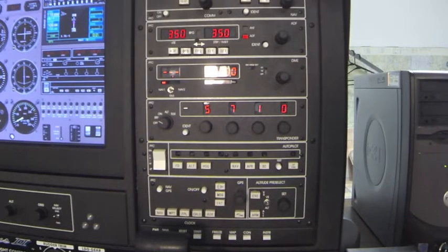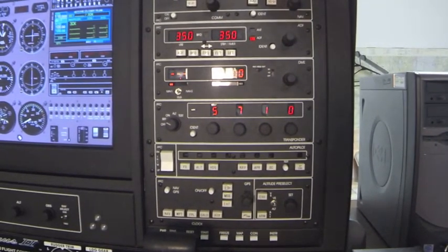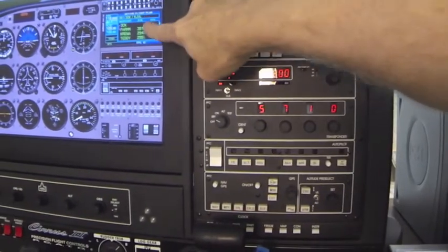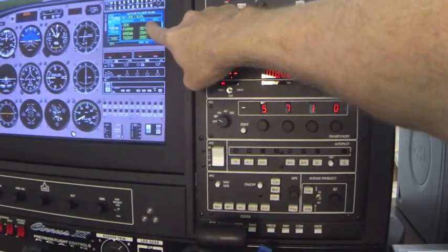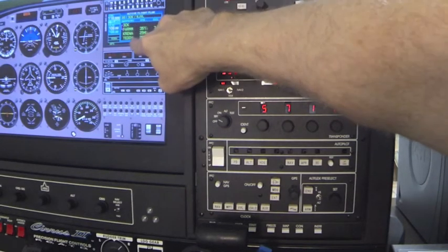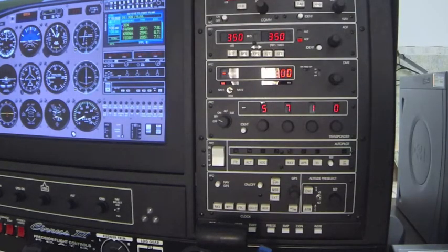And then we have some routes that are saved. I'll press flight plan, and I'll turn this to the second page, turn the cursor on, move the cursor down to 3CK to Janesville. I'll press enter and menu and activate that flight plan. And now over here you would see that the flight plan goes from 3CK to Farm Intersection to Corinna to Teddy, and so on and so forth until it gets to Janesville.